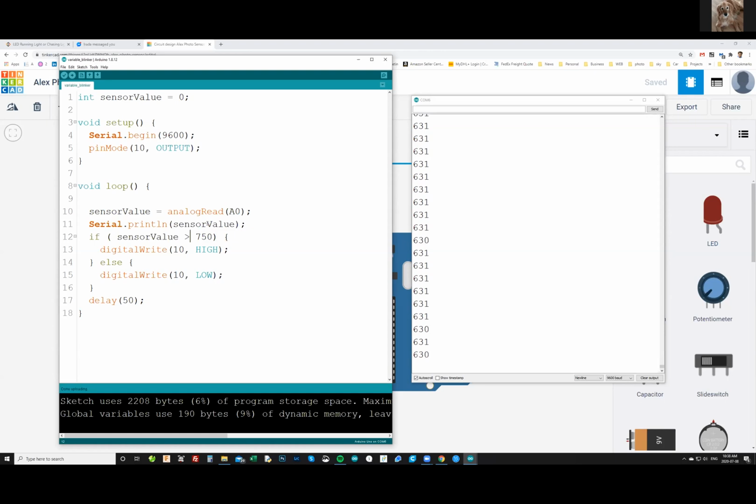Do both resistors have to be the same? No. The one from the LED I have is 220, and then the one through the photoresistor, I forgot what it's called, is 1,000. Do I need to make it higher or something? 1K, right? It's still not working. Because your numbers are below 400 and then go over 400, right? The one on the LED is correct, but for the photoresistor, you need 1K, right, Alex? Yes, I used 1K for the photoresistor and 220 for the LED. That's exactly what I did.